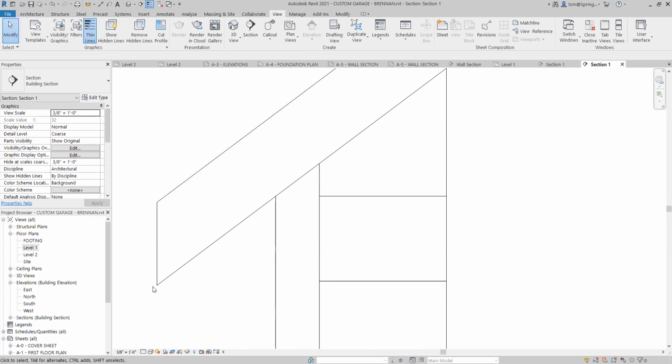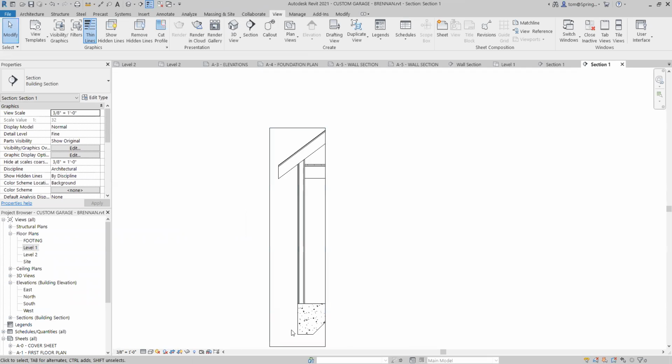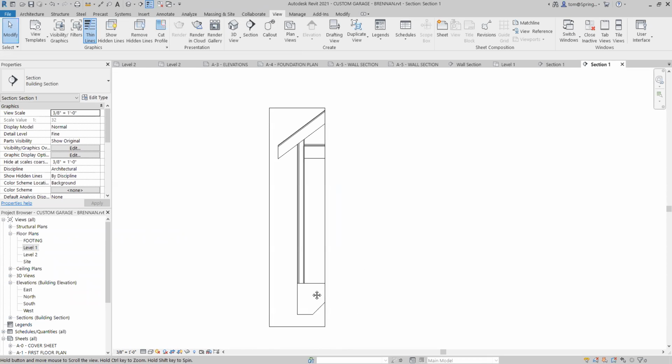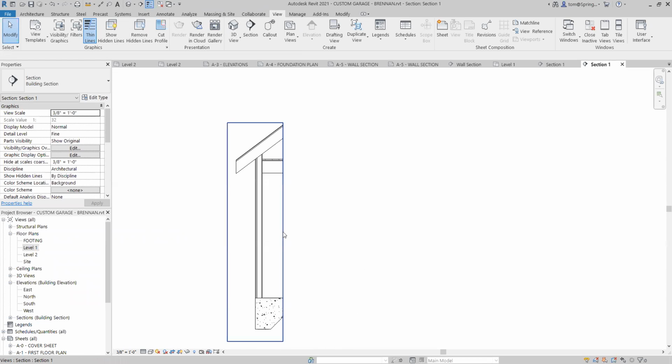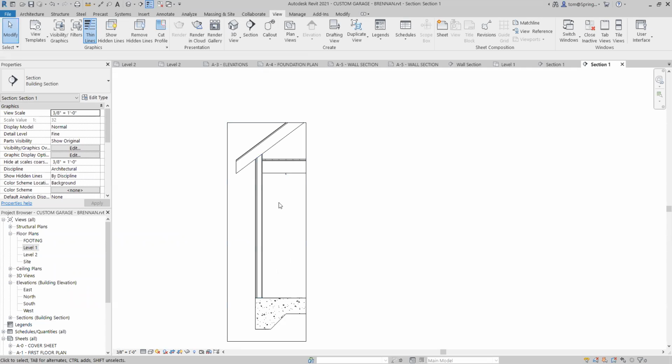But if you're not seeing the lines, check this out here. You've got coarse, medium, and then fine. You want to make sure you're on fine. Fine gives you the detail that you want. It gives you the max detail. Now, once you've got that, you've got a start. But you're missing some things, which we talked about. You do have your fill route down here in this section. And I may open this up just a little bit, just to pull this over a little bit like that. That gives me a pretty good place to start.